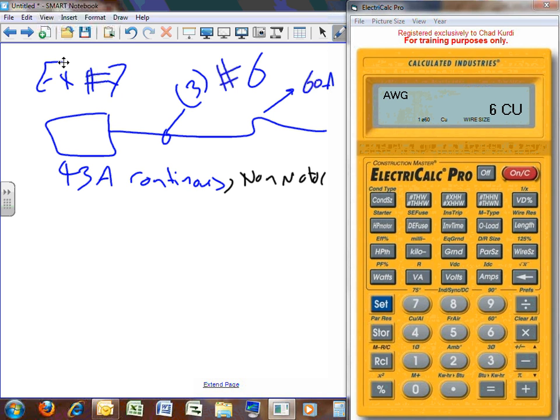Whatever you derate, when you derate and size a conductor, whatever you come up with, if it came up with something less than number 6, number 6 rules. Because that's under normal condition, that's how you size the system if there's no derating. Derating is an abnormal condition. You should come up with a larger conductor, not a smaller one.